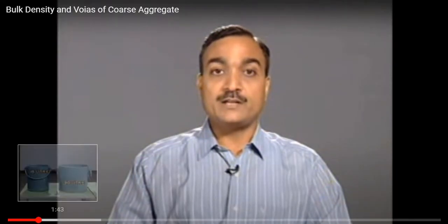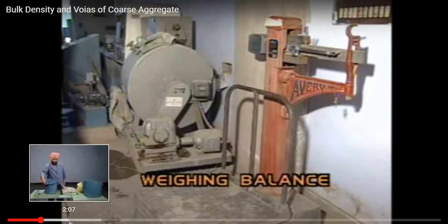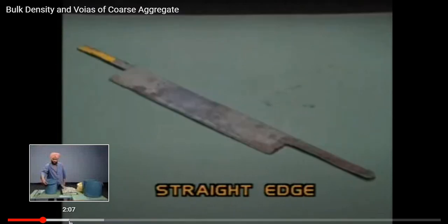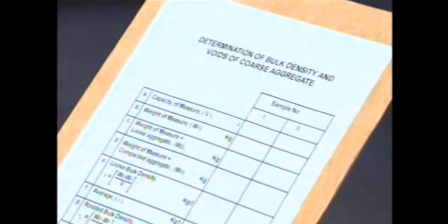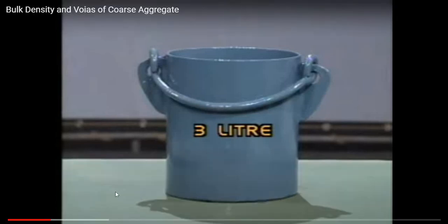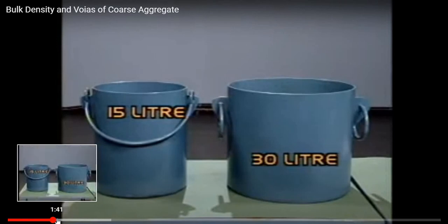For determining the bulk density, the apparatus required includes weighing balance, either electronic or mechanical, tamping rod, straight edge, aggregate sample under test, and the observation sheet to record the readings. We also need cylindrical metal measure of 3 liter, 15 liters or 30 liters capacity.